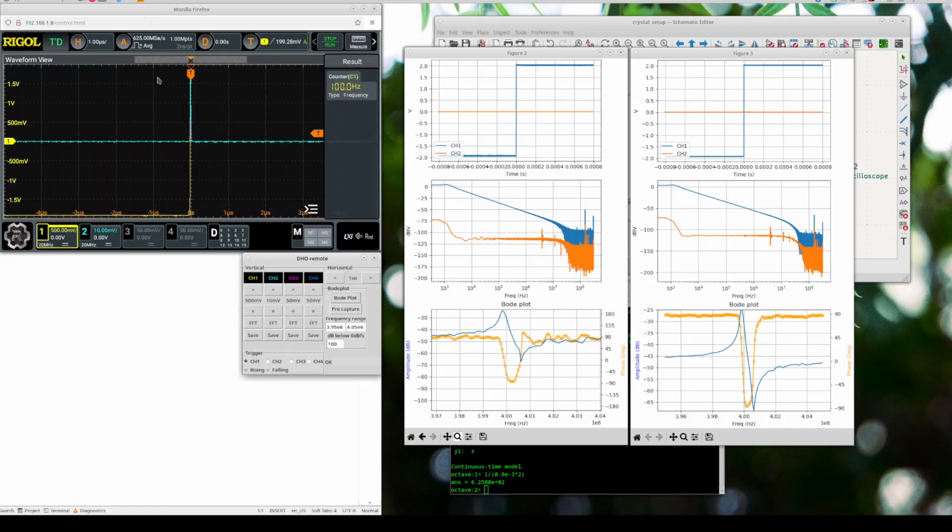Now there is still 625 megasamples per second, but once I lower the time base, I really need to lower it a lot because of the memory depth. Now at 200 microseconds per division, the sample rate drops to 312. I can do that a bit further. Let's take 1 millisecond. So it's now 62 mega.